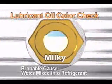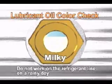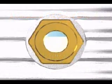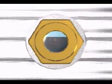If the lubricant oil is milky in color, water might be mixed in the refrigerant. These cases usually happen in case of mistakes in service operation or insufficient vacuum operation. Since it's liable to happen on a rainy day, do not work on the refrigerant line on rainy days. When the lubricant oil color changes, find the relevant cause and repair it.